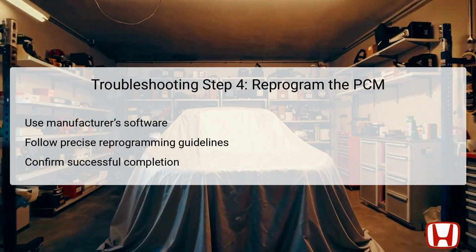Once power supply issues have been addressed, proceed to reprogram the PCM using the manufacturer's recommended software. This software is specifically designed to ensure the PCM receives the necessary updates and that these updates are applied correctly. It is vital to follow precise reprogramming guidelines to avoid encountering the same error again. During the reprogramming process, monitor for any failures or interruptions, as these could signal underlying hardware problems or external factors affecting the PCM. After the reprogramming is performed, it is crucial to confirm successful completion by conducting a subsequent diagnostic scan to ensure that DTC P0602 does not reappear. Properly executed reprogramming can restore normal functionality to the engine control systems.